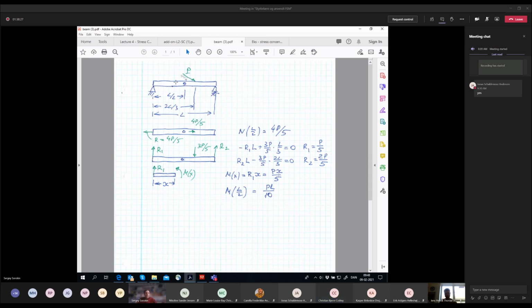So you see, it's a very natural question. Here we discuss the equilibrium from the helicopter viewpoint. We consider this whole structure, and we are interested in the force resultants or stress resultants acting on the structure to ensure its equilibrium. So it's not zooming into how the stresses are actually distributed. This is the story of the resultants of the stresses, and these resultants ensure the equilibrium of this body. I think this is what you've been asking. Yeah, that was it. Cheers. Good.